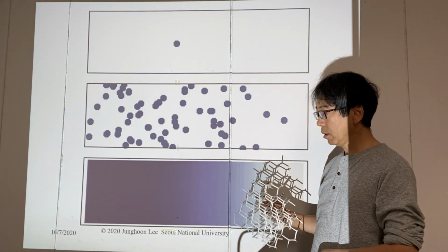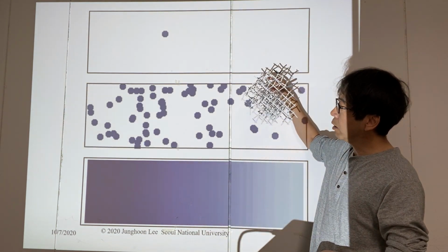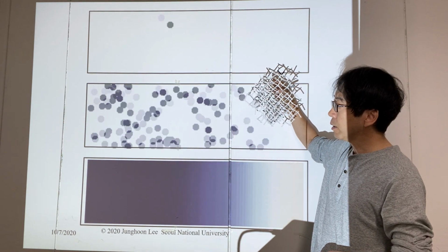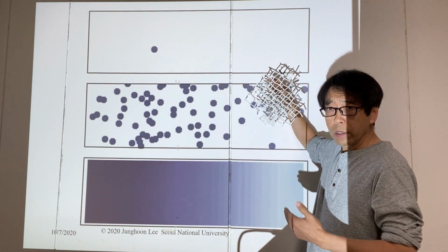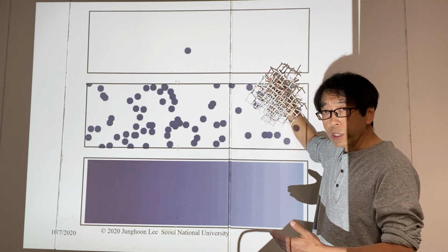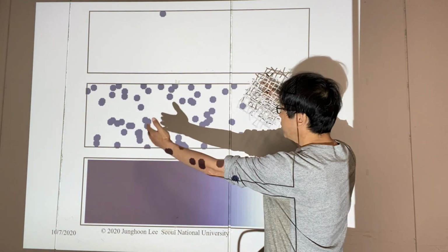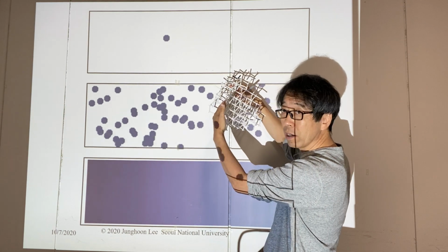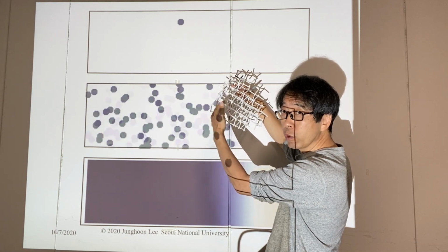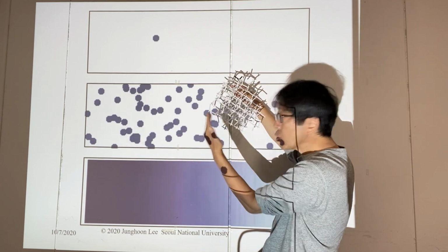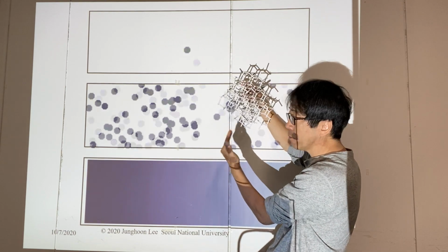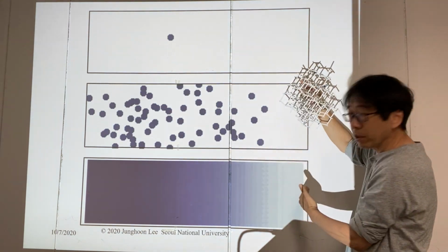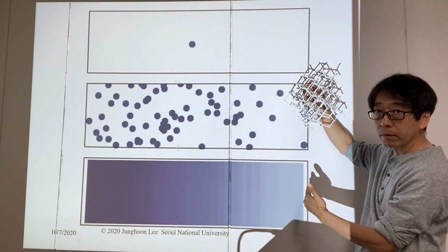And then you would like to elevate the temperature so that at high temperature, diffusion is promoted. Diffusion of these impurities into the lattice of this silicon crystal will be promoted, and they will actually migrate. This dopant will migrate and then diffuse into the silicon crystal.